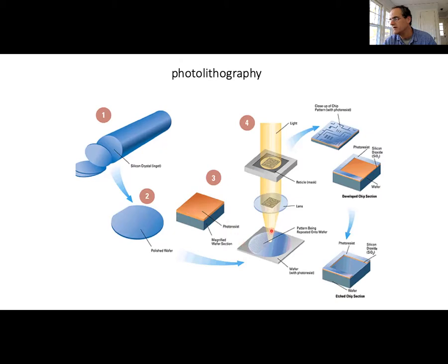And now we can do a trick. We can make a diagram, a reticle or a mask that lays out some of the circuit that we want to build on the silicon wafer. And then we can use photolithography. We can transfer that pattern to the silicon wafer by exposing the wafer with ultraviolet light through the mask and focusing an image of the mask onto the crystal.